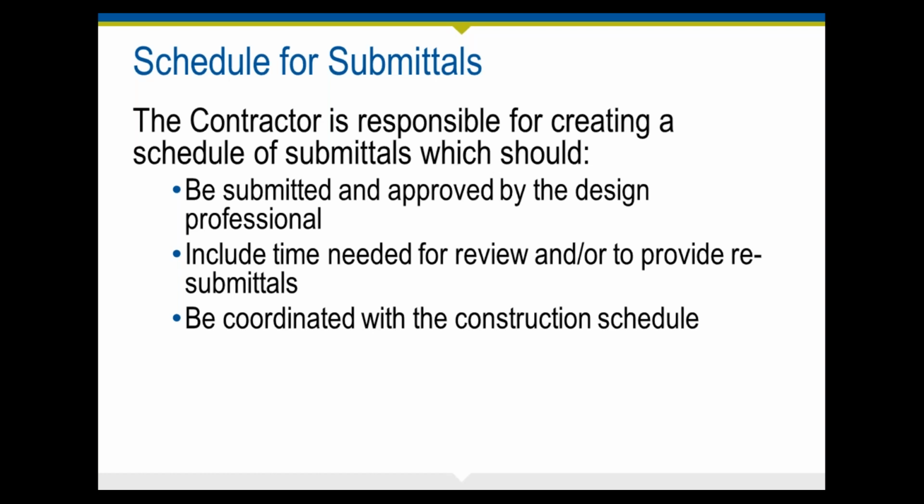So the first thing you want to do, especially on a large project, is to ask as a preliminary matter and make sure that the contract documents require that they have a schedule for submittal, especially for large projects, because that schedule tells you exactly how much thought the contractor has put into the submittal process, what it takes to get it approved. Then once the submittals are approved, oftentimes that kicks off fabrication for specialized equipment that is specific to the construction site, but until your shop drawings are approved, that doesn't start.